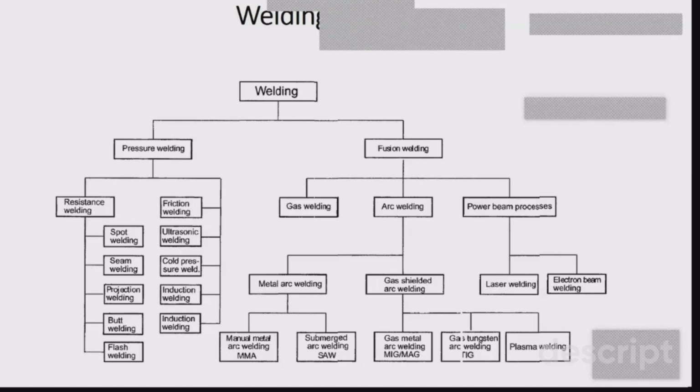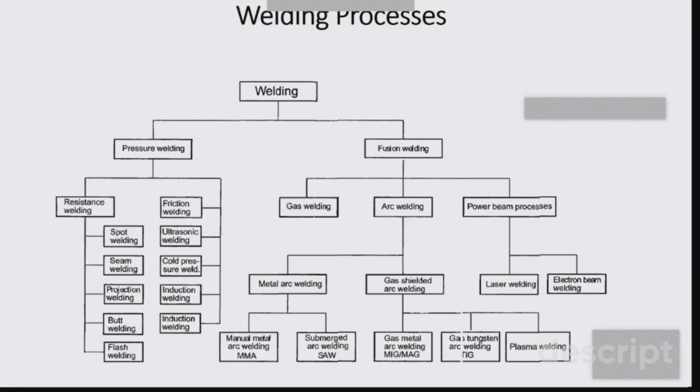The ingredients of the flux also have two components: the oxidizers and the cleansers. What are oxidizers? Oxidizers are the ingredients which are used to prevent oxidation, and sometimes the base metal or your filler wire may contain some contaminants which may result in inhomogeneity in the weld metal. The cleanser ingredients perform the cleaning operation. They dig out the impurities from the weld metal, and then they form some slag over the surface of the welded joint. Later you can break this slag and chip it off to get cleaner weld material. So this is the manual metal arc welding process.